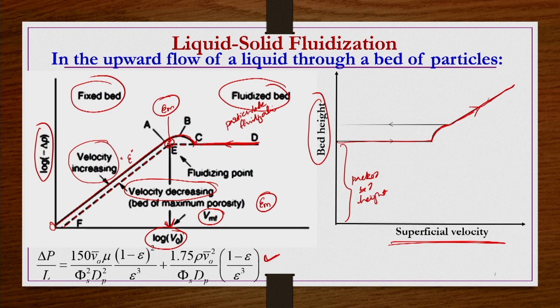Okay. Now, you fluidized it sufficiently, you can see the fluidized conditions, okay, a proper fluidized condition, not just expanded or minimum fluidized conditions. After reaching that sufficiently high fluidized condition, you are decreasing the velocity. When you decrease the velocity, you can see that the bed height gradually decreases with the decreasing superficial velocity, but after this point it is not going to come back along the previous curve, but it is going to be constant like this, because by the time the velocity decreases to this point, the particles are settled and resting onto each other, and further compact packing of those particles is not going to take place. So, that packing height is slightly higher than the initial packing height. So, while decreasing the velocity, the height would be slightly higher, and because of this slightly higher packing height, the voidage is going to be higher. So, the pressure drop is going to be lower, as we have seen in the previous curve.